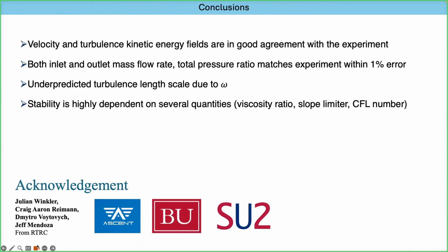When you said one of the mesh requirements is a y plus less than or equal to 1, have you ever tried using wall functions? I'm sorry, could you repeat? The question is if you ever tried wall functions because of this y plus 1 requirement. Have I ever tried the wall function? No. I did not use the wall function, and so far I have been trying to resolve the wall using a small y plus. Maybe you can try it and see if it helps. Yeah, that's a good point.